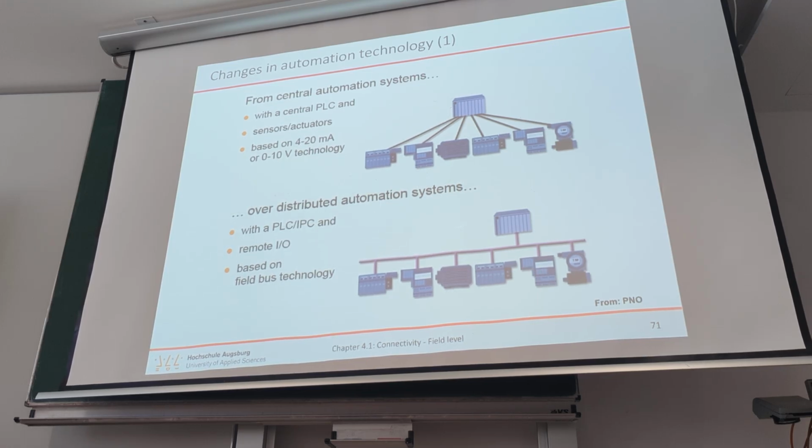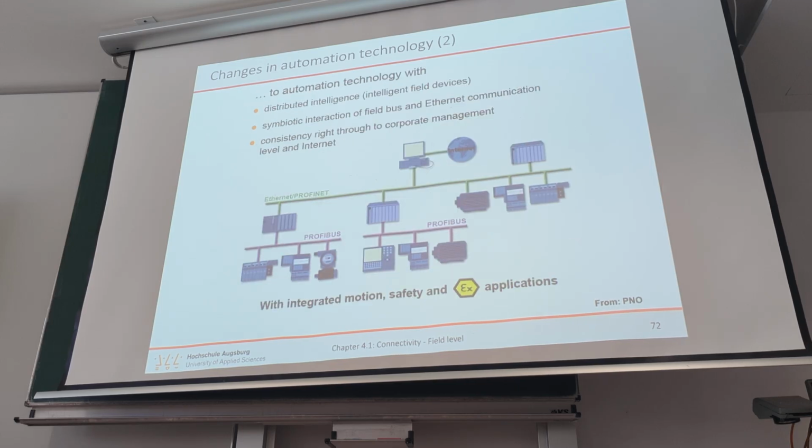You can do that with a field bus, but the switch costs like 10 cents, and then you need $2 or whatever for the field bus connection, and it's just not worth it. So that's why we have this layered architecture, and we also have old bus systems and new bus systems.